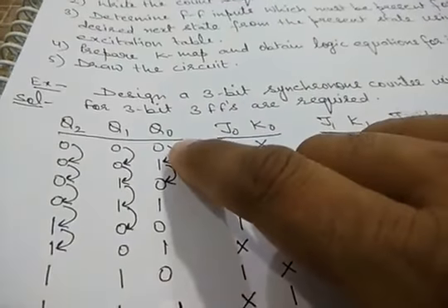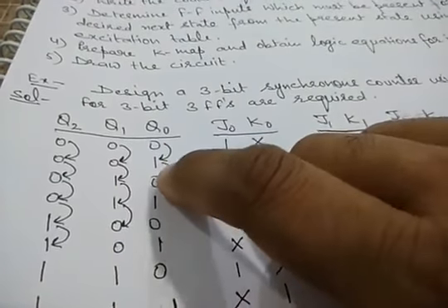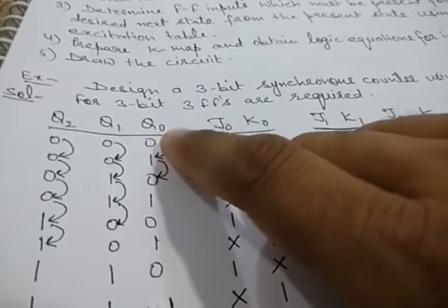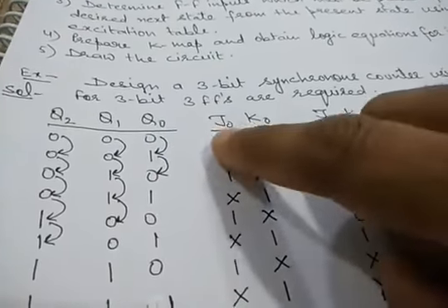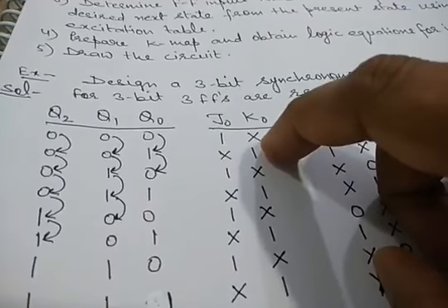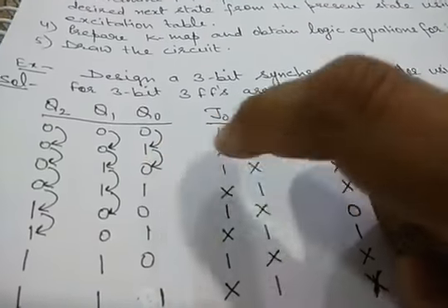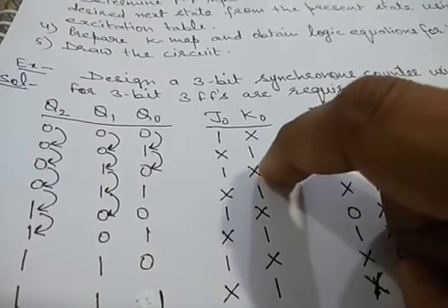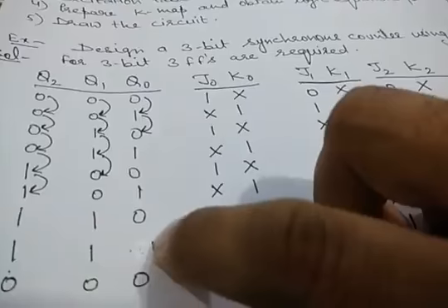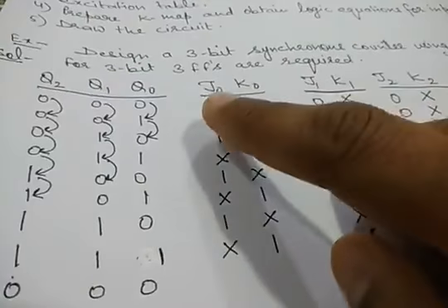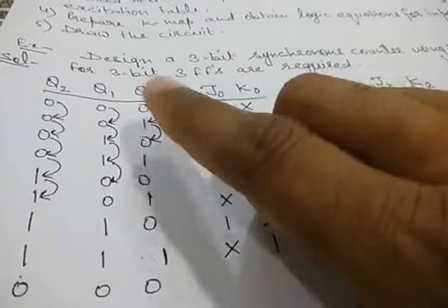Here Q0 is 0, that is, the present state is 0 and the next state is 1. So whenever we have the present state as 0 and the next state as 1, it will be 1 cross or don't care. Next is 1 to 0, so it will be don't care 1. Then 0 to 1, 1 to 0, 0 to 1, 1 to 0, 0 to 1, and finally 1 to 0. So depending on the excitation table, we will be giving the inputs for J0 and K0